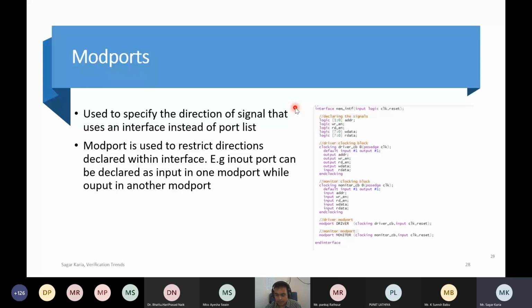Now in SystemVerilog, another major concept is randomization. The OOP concepts are done. Now I am going to focus more on the important things you can get using SystemVerilog which are not there in Verilog. You can do constraint-driven test generation, which allows you to automatically generate multiple tests for functional verification. This random testing is far more efficient than traditional directed testing, which is done in Verilog.